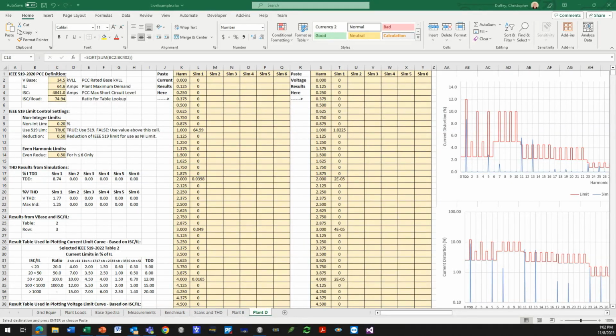Instead of simulating the phasing and the cancellation, to be able to get the work done, because as a consultant, you've got to get the answer and you can't take forever. And phasing information is kind of nebulous, and it's unknown unless you actually get some data to track it and understand it a little better, maybe statistically figure out where your phasing is sitting at each of your individual harmonics. You've got to do something to get your answers. And so I have historically set them mostly to 0 and then dropped magnitudes of the individual sources slightly to make the result back at the substation appear reasonable.